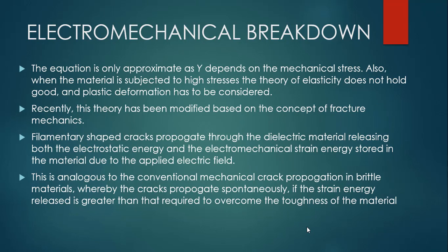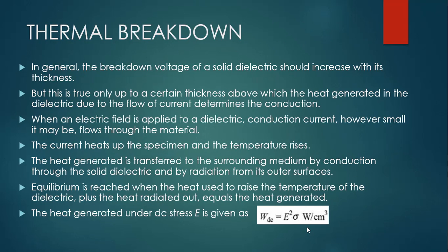Now we'll go to the thermal breakdown. In general, the breakdown voltage of a solid dielectric should increase with its thickness, but this is true only up to a certain thickness, above which the heat generated in the dielectric due to the flow of current determines the conduction.